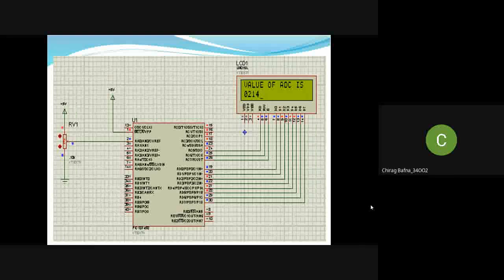In recent years, for many applications where space is a critical issue, using such a large number of data pins isn't feasible. For this reason, serial devices such as the serial ADC are becoming widely used. While serial ADCs use fewer pins and their smaller packages take much less space on the printed circuit board, more CPU time is needed to get the converted data from the ADC because the CPU must get data one bit at a time instead of in one single read operation as with the parallel ADC.